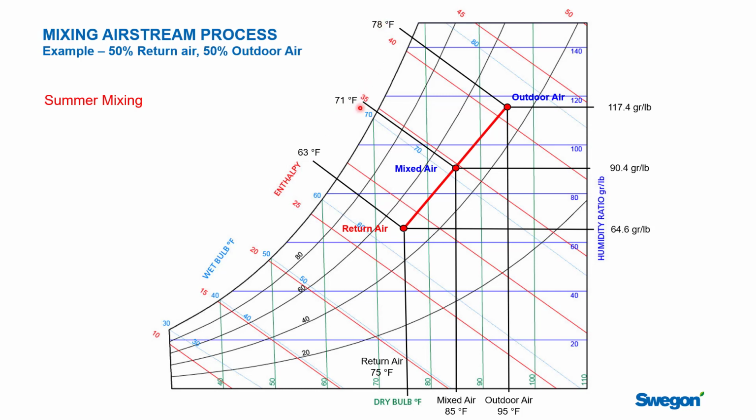Over here on the wet bulb, it's very close to the same thing. Our wet bulb is coming in at 71 degrees, and it's almost halfway in between these two. These lines aren't perfectly parallel. If you use software, and you're measuring to 1/10 of a degree F, you'll realize you won't be exactly 50%, but it's because the formulas aren't exactly linear, and the software is just doing it to a more accurate number.